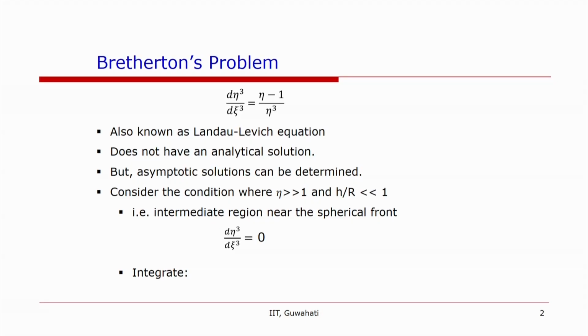Okay, so in this lecture we will continue the discussion about the Taylor flow. In the previous lecture we were talking about the Bretherton problem, and we developed a partial differential equation for the bubble profile, or for the bubble interface, in the non-dimensional coordinates eta and psi.